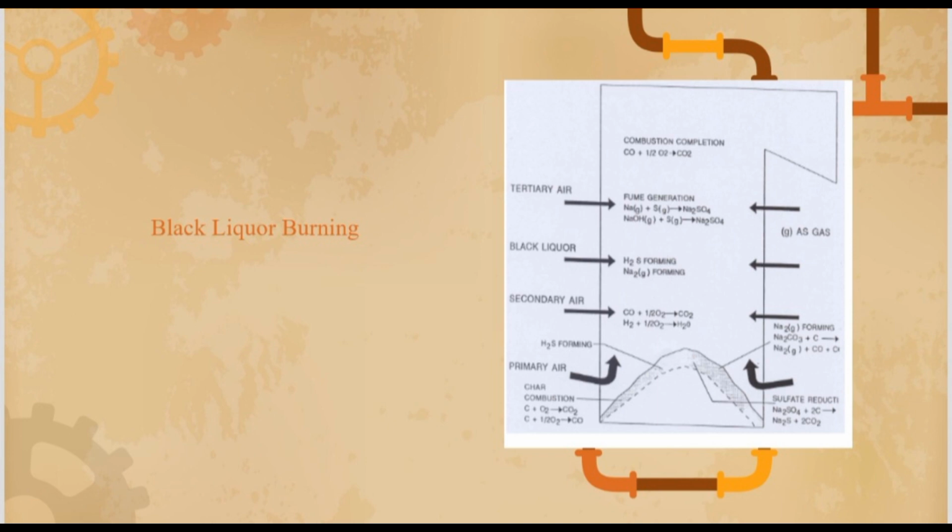Combustion air also enters the furnace through ports located on the walls making up the furnace cavity. There is considerable variability in how air is introduced. The lowest air level is called primary air. Primary air enters close to the hearth from all four walls.